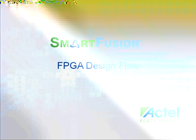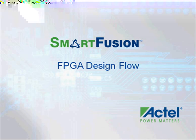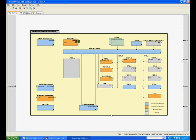To connect the MSS master APB port to the Fabric, you must right-click it and select Promote to Top Level. We are now finished configuring the MSS for this design example. Click the MSS Generate button to complete the MSS design and turn it into an HDL component.